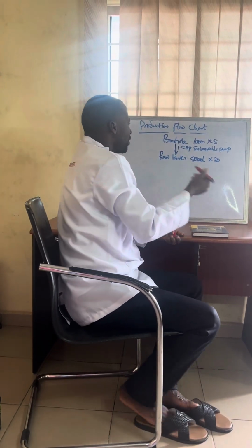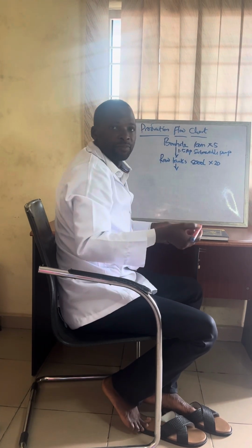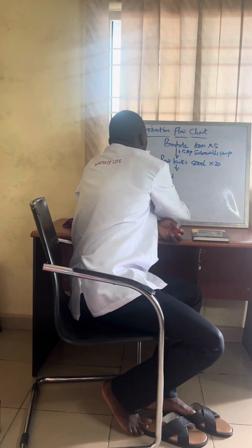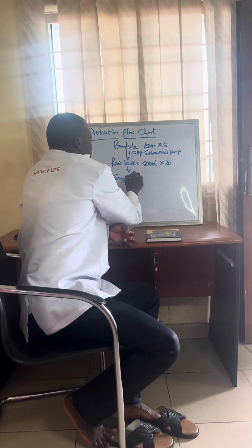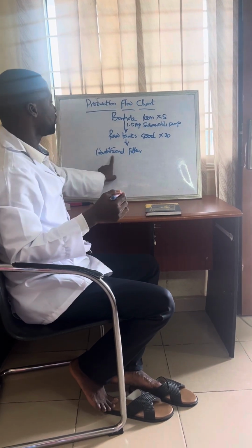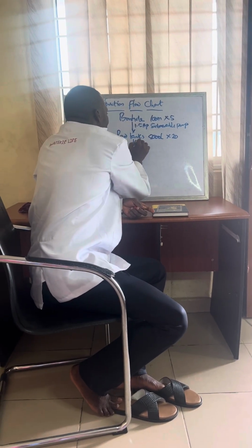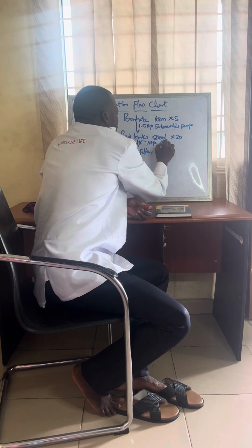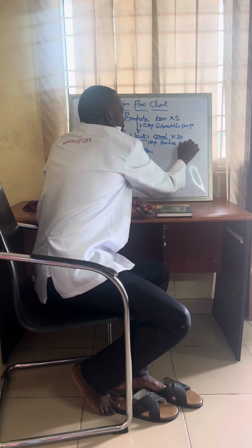Then from the raw tanks, where does it go to again? It goes to your filtration media. It goes to your industrial sand filter. Now what pumps the water through this industrial sand filter? It's your stainless surface pump. Let's say 1 horsepower stainless. It has to be a stainless surface pump.